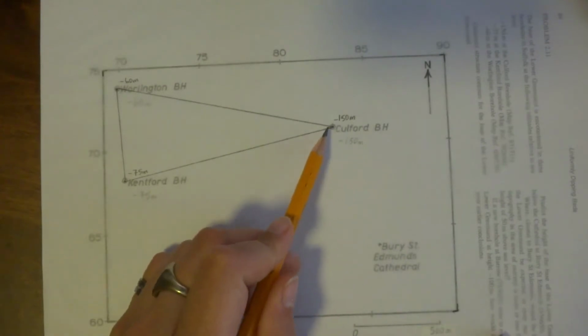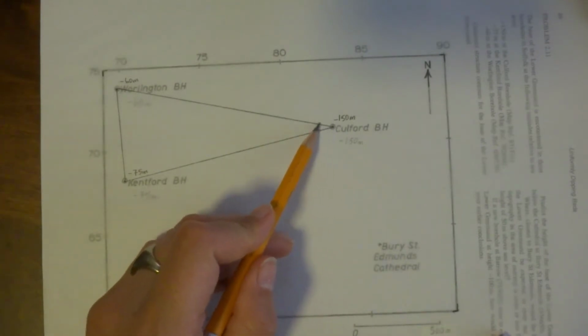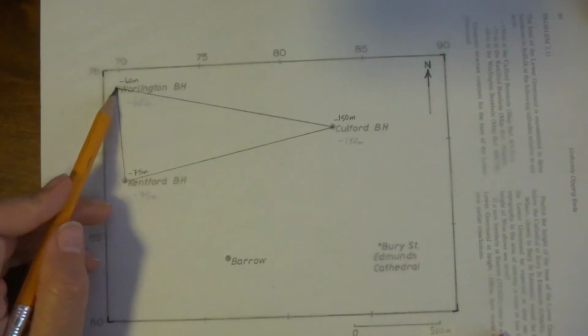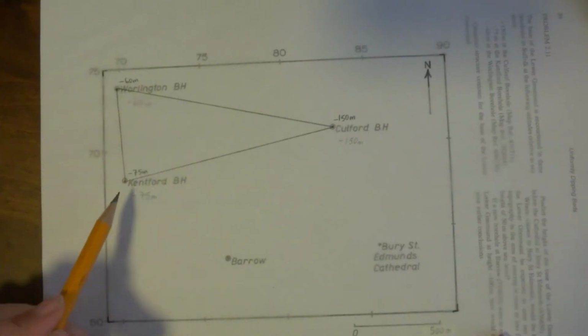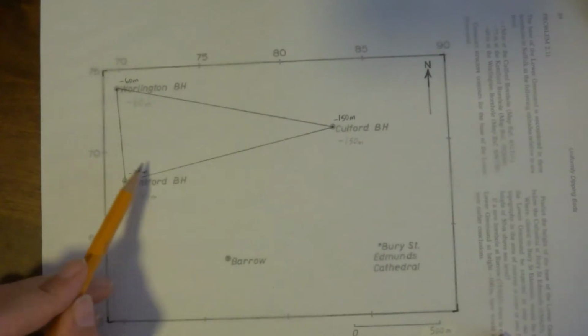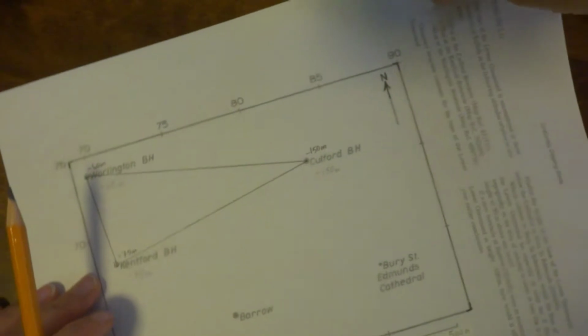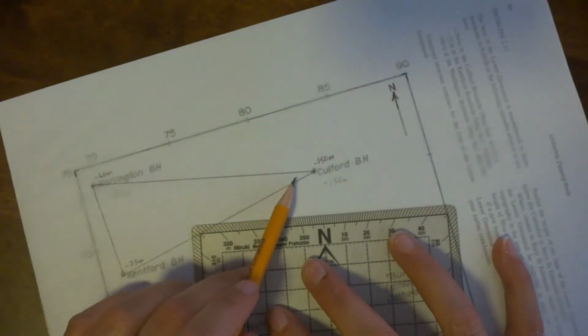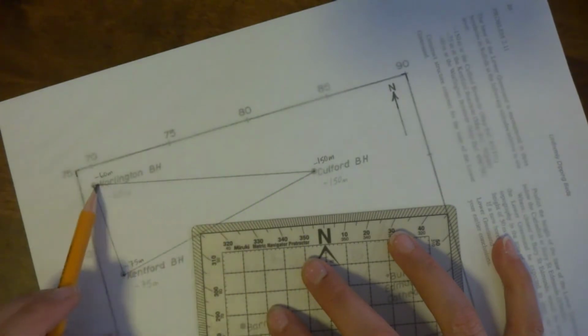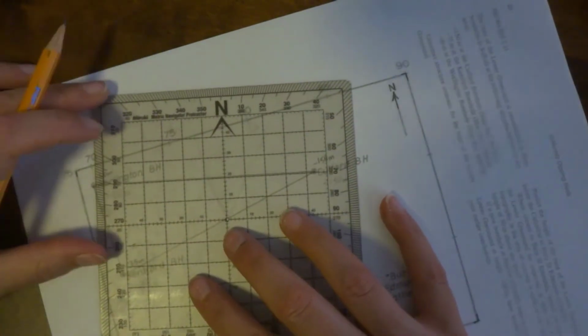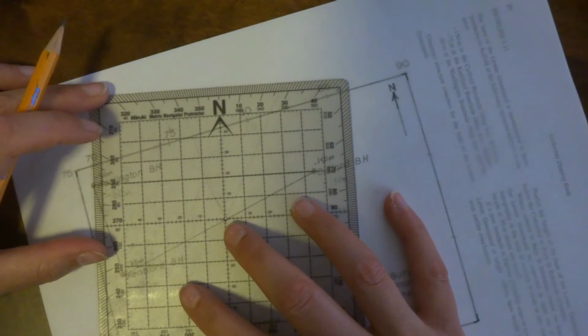So to determine the strike line, we know that somewhere along this line, the elevation of the lower greensand formation will be minus 75 meters, which is equal to the depth at which the unit intersects the Kentford borehole at minus 75 meters over here. So to do that, we extend a section line perpendicular from this triangle using our Douglas protractor as a handy tool.